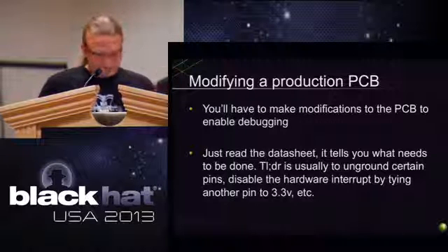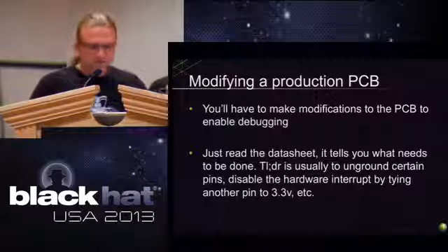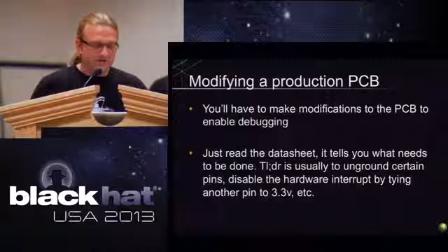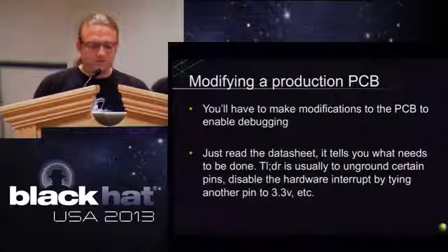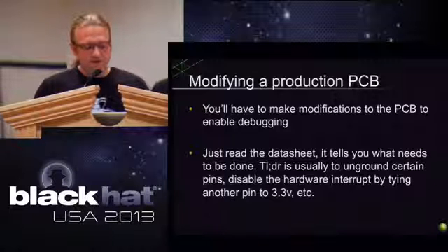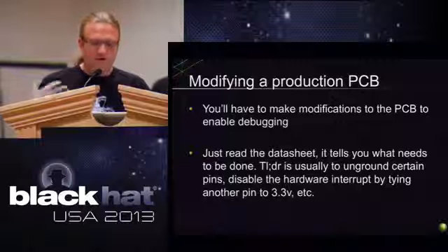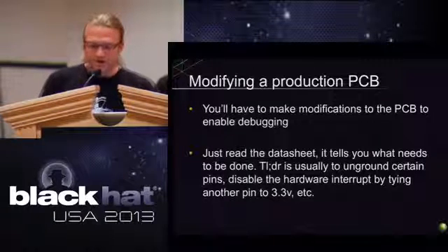Yeah, so typically what we find, and this is just general, not really Teridian specific, is that what we're looking for when we want to dump firmware is just to shift the chip into a different mode. So it's ungrounding a pin, grounding a pin, crossing a pin with power. These are how the hardware actually works. So this is what we're going for when we're really trying to understand.